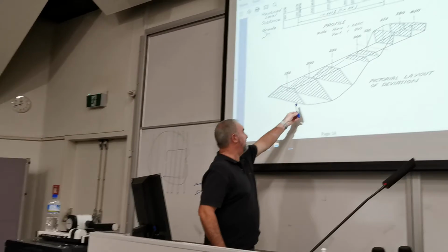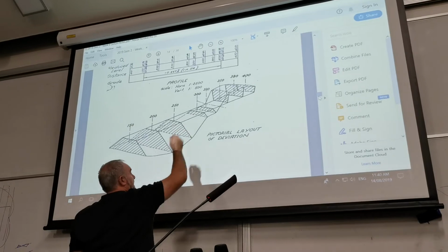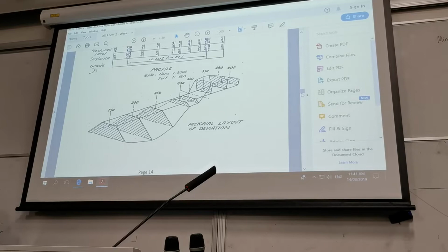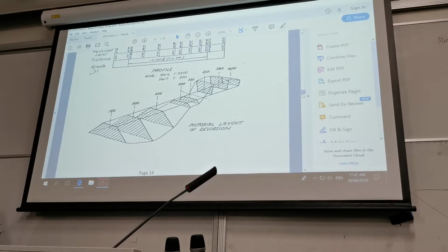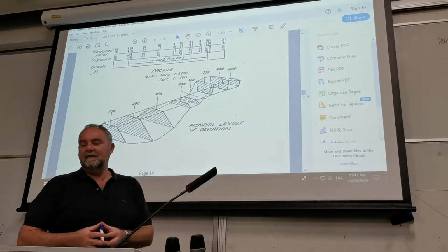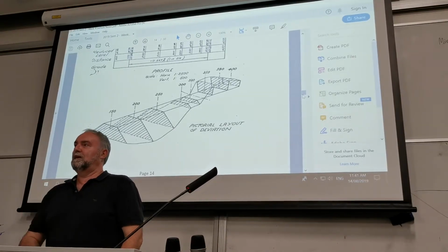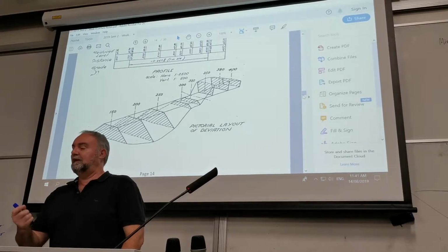And the way we work out our volumes is we have a distance between each one, and we have an area of each one, and we can work out our cubic meters from that. It's not quite as easy as that. I will introduce you next week to the Prismoidal calculation sheet, my famous one. You'll get to take it home in a spreadsheet. When we enter these values into it, it pops out an overall volume. It's the same formula on that sheet that 12D, Civil 3D and MX Road use.